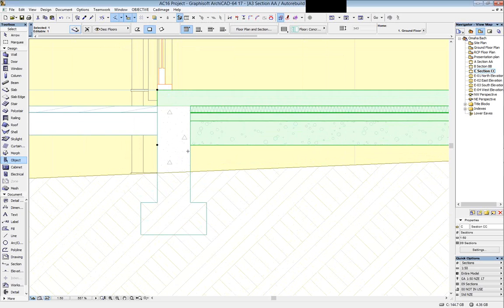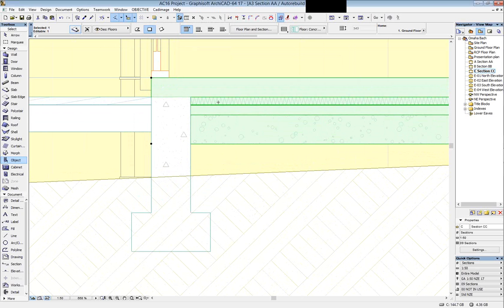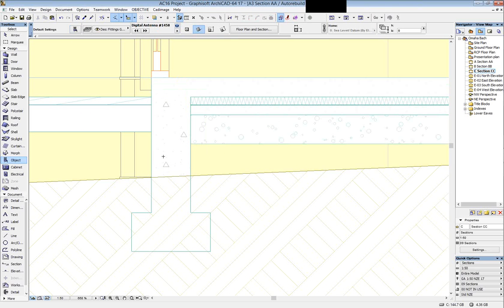So as you can see, this is much more than just insulation. I've got an insulation skin, some DPC, some sand blinding, and some hardcore fill. Notice as well that the two black nodes that signify the edge of the slab are actually underneath the edge beam, but they're not actually. If I select that edge beam and delete it, it goes right to the end. If I undelete that, the beam cuts them out.